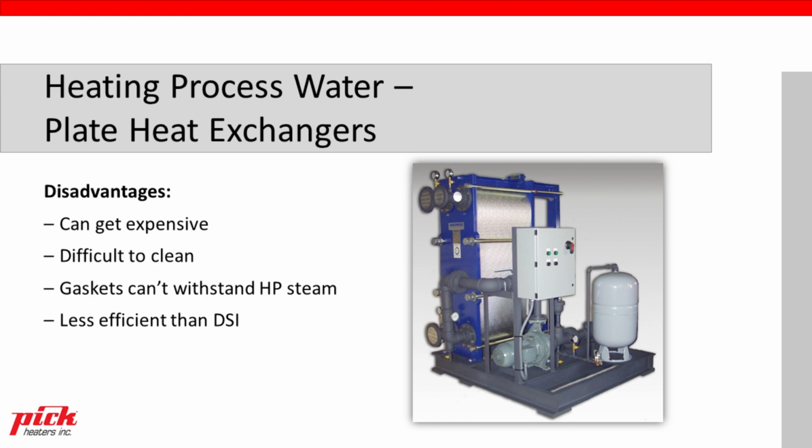Some of the disadvantages with this type of plate heat exchanger are, of course, they can get expensive. They're also difficult to clean. If you have to clean them, obviously the end has to be pulled off and all the plates have to be separated and cleaned or disinfected. So it's a time-consuming process.